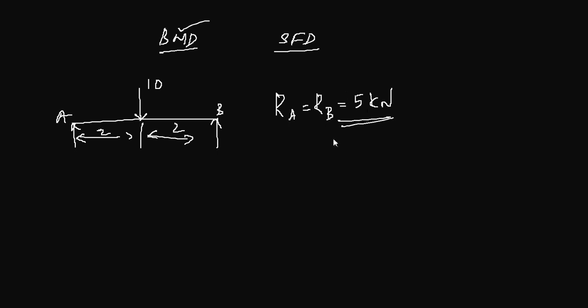Now, as in the shear force case, we use the method of sections in calculating the bending moment as well. So you take a section between each force point. You have a force point here, another here, and another at point A. You can calculate from either end, A or B, but once you decide the point you calculate the bending moment from, make sure you keep the same point for every analysis of that problem.